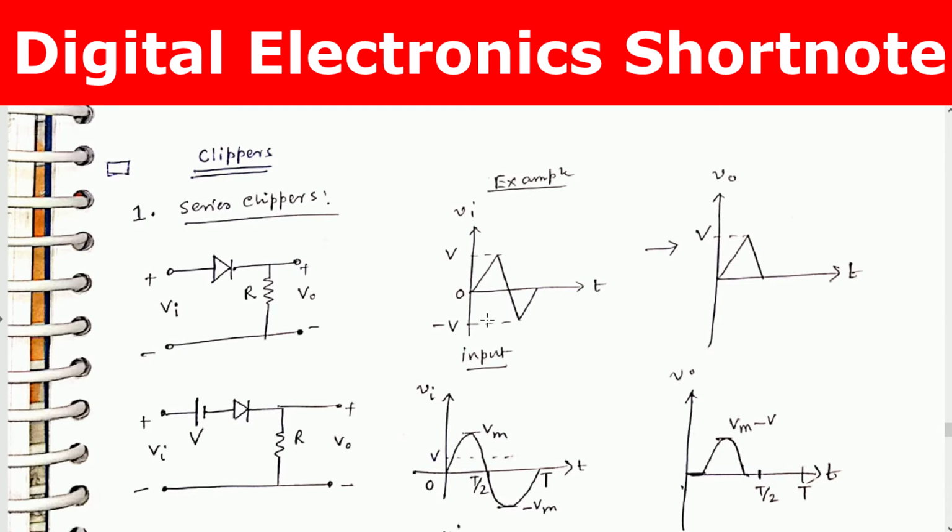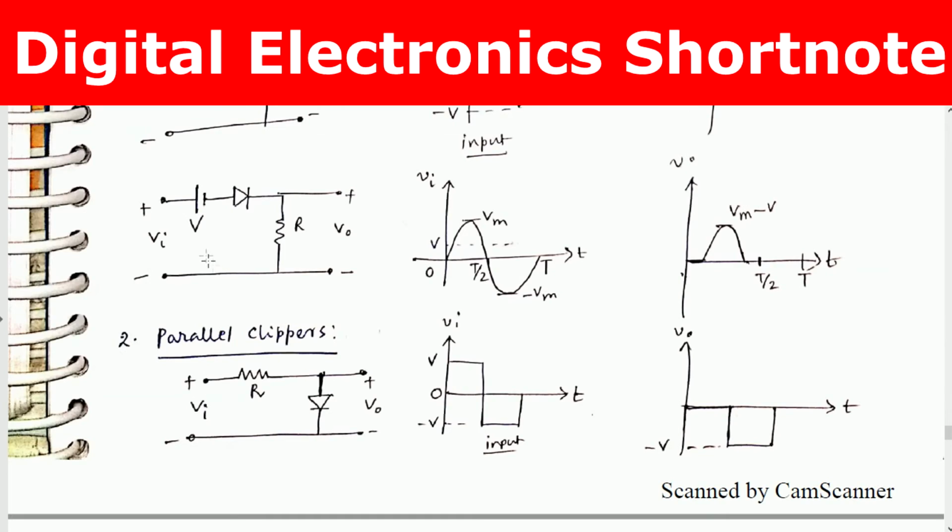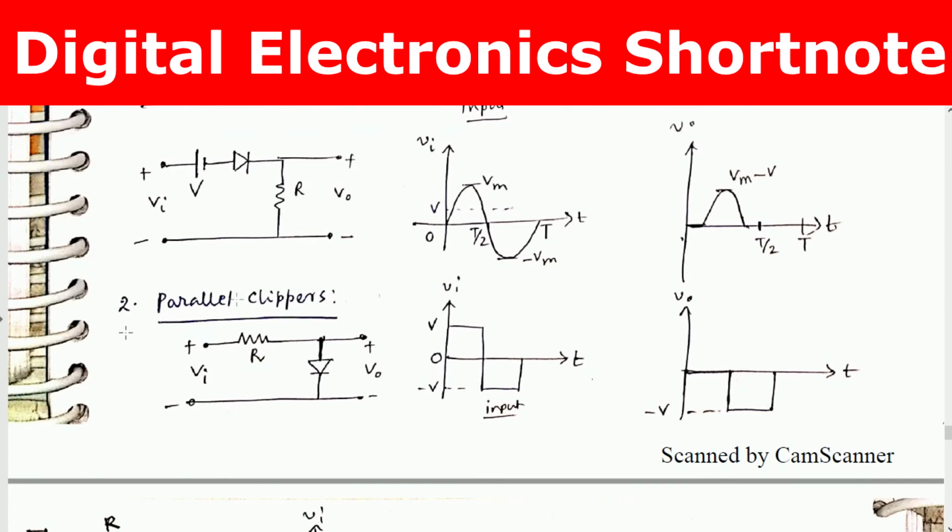Now clippers. So this is the circuit for a clipper. Diode, resistance. If this is the input, it clips this negative portion. For this we have introduced a voltage V. Then it clipped this negative part, but it is producing an output which is less than V minimum because a voltage source has been used here.